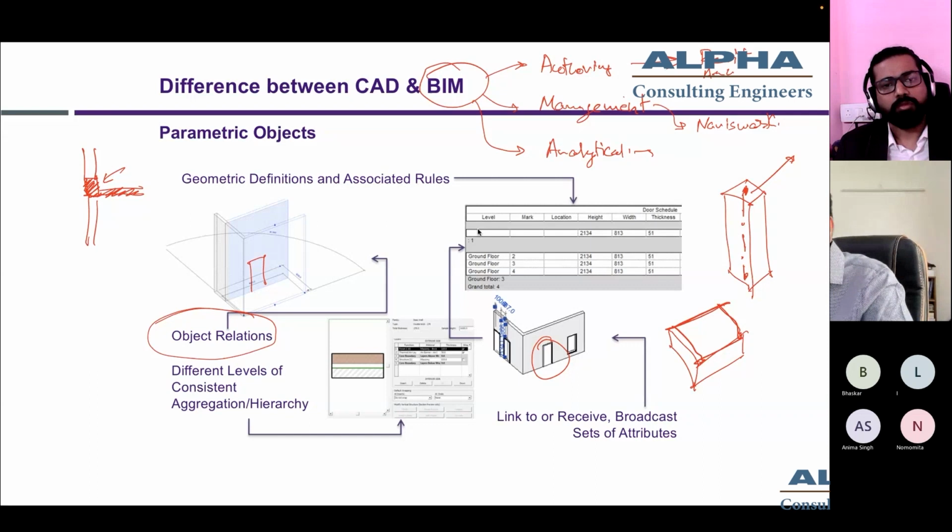So this helps in the detailed design processes, detailed engineering processes, when you have analytical components being created alongside the representation of actual building elements. And these sets of analytical components create analytical models in various formats. One such format, let's say, is SAF nowadays, created with the help of ArchiCAD, or with the help of the APIs, the application programming interface, inside these tools.